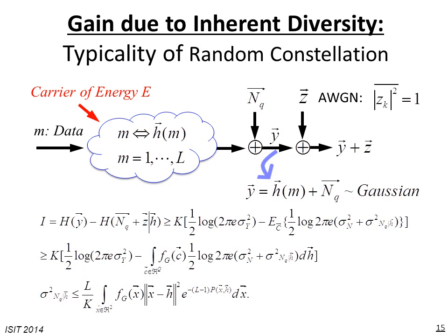Consequently, the expected value of the capacity will tend to the capacity achieved through random coding over an AWGN channel, which is known to be the maximum. When the average meets this upper bound, then with probability 1 different realizations achieve the capacity of the underlying 1 times 2K Gaussian channel.